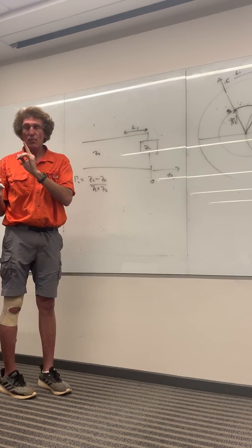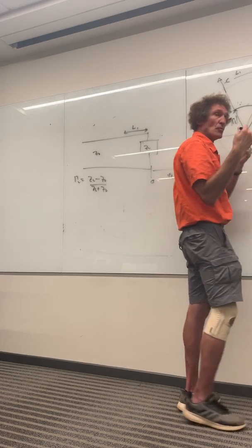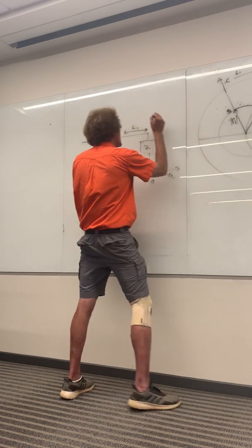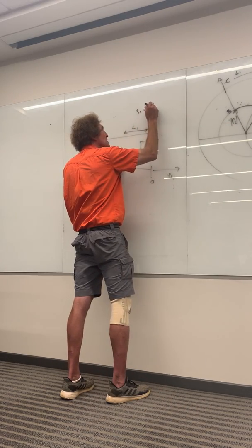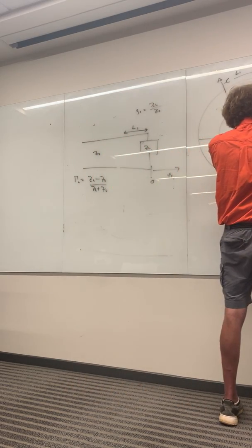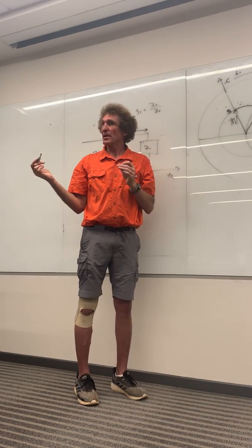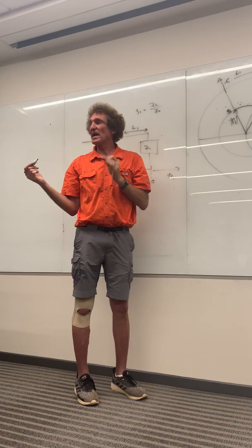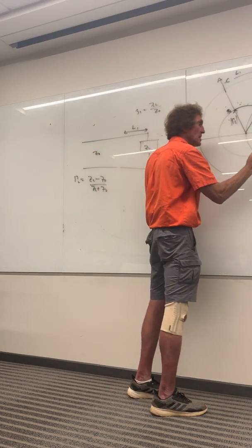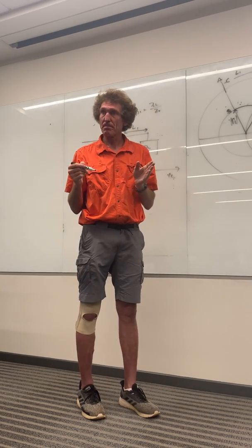Now, this is important. Right here, my value of impedance at that point, normalized impedance, mind you, ZL normalized, remember, is going to be capital ZL over Z0. Well, now the normalized impedance right here is going to be 1 plus jX. It's got some other value, right? Everybody hear me on this one? Now, jX is a reactance. We could also move to this point right here. This would be 1 minus jX. It would be the same value of X, but that would be negative, right?